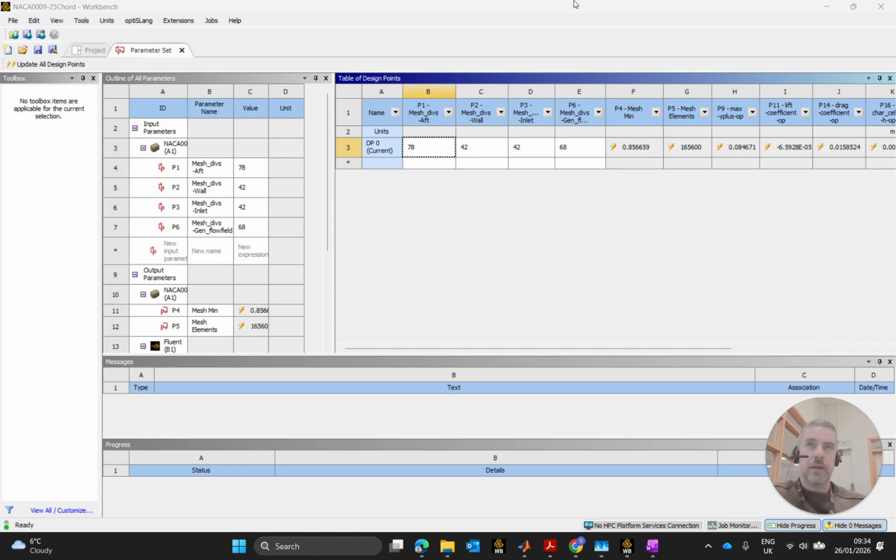Okay, we'll find in this method typically that if we refine too much, we bring brand new physics into the equation. Right? We bring brand new physics into the flow field which weren't earlier captured in a coarse mesh, where we just averaged over them, brushed past them because we weren't refined enough to see them. But when we do refine, we see new things come in, and that is going to have implications, number one, to our apparent order, which is really a description of our numerical behavior, but also to our grid convergence index value.